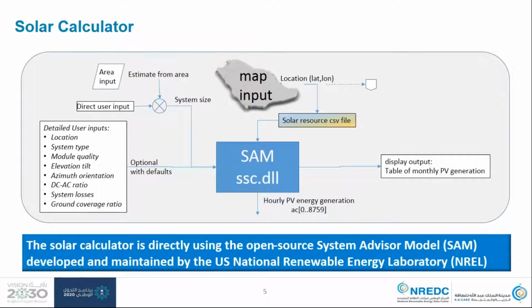So we have used SAM for the solar calculator, and you could say it looks a lot like the NREL PV Watts site. You're presented with a map interface, and you select the location, and then you can either draw a rectangle to represent the area of your system, or you can just directly enter the system size.